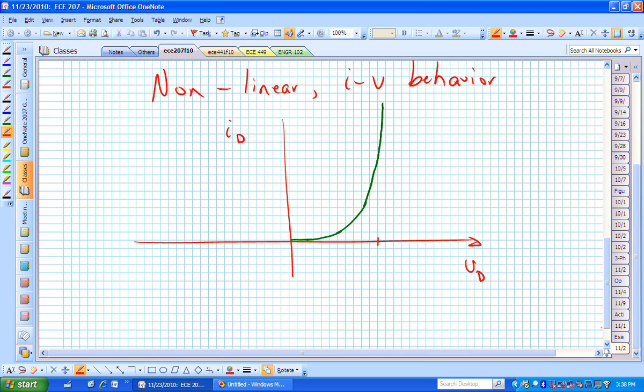It's not very big. And in terms of units or scale, this might be milliamps that you want flowing through your diode. Question? The question was, does the current go to infinity? Ideally, yes, it will support an unlimited amount of current, but for a practical diode, you can only put so much current through it before it starts being destroyed. You smell it, or smoke starts being emitted from the device.